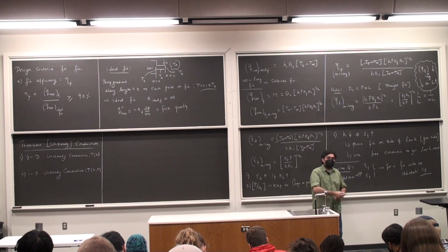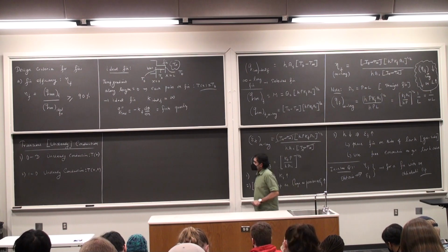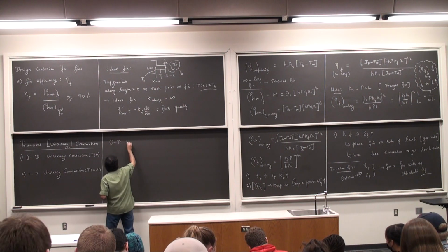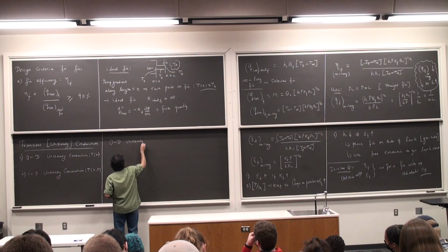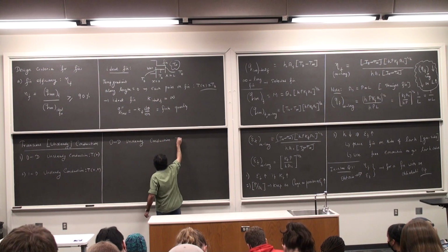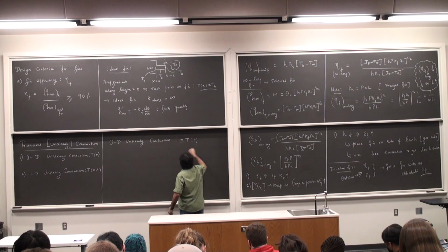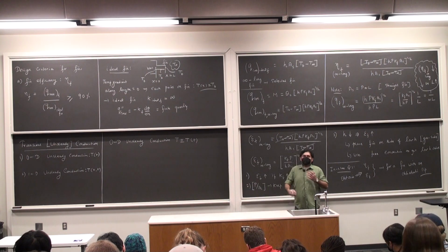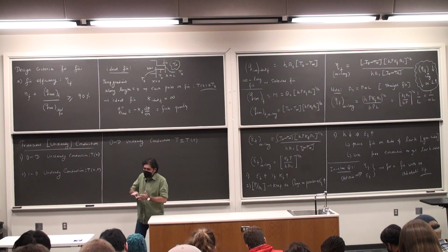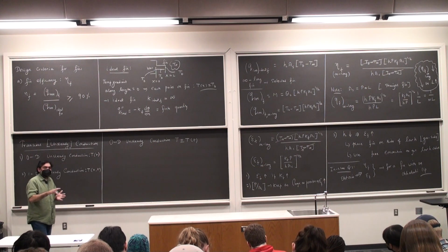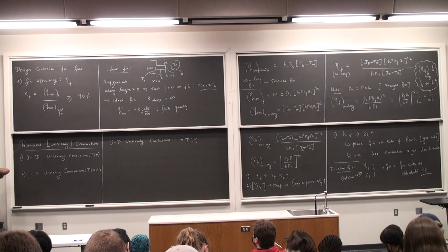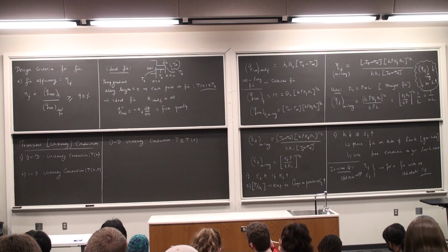You use finite element or boundary element methods for that. Okay? So let's start with 0D. And why I'm looking at 1D unsteady as well is that I want to come up with a criterion that says, if certain conditions are satisfied, then I can model this 1D unsteady conduction as a zero-dimensional unsteady conduction, so that spatial effects are ignorable.